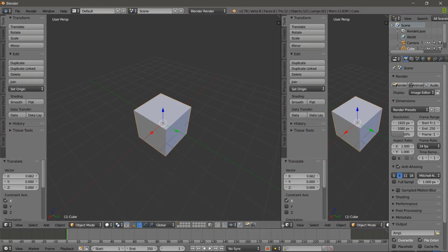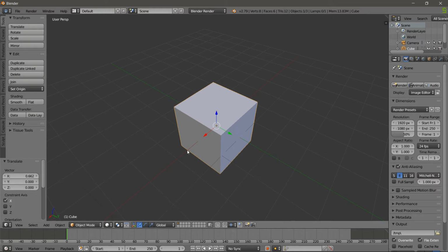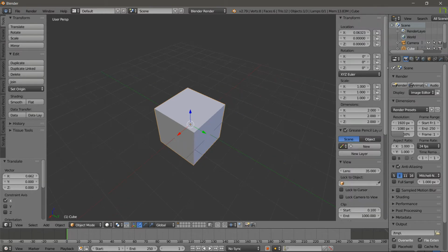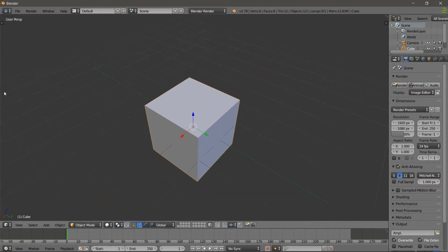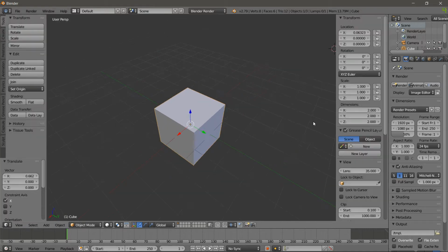Now the next thing I gotta cover is the main layout. So there are many hotkeys and stuff. I'll just teach you the basics. Usually this will be open. What I did is press N to open and close this, and T to open and close the tools tab. You can also use these plus keys, but this is more efficient, right?